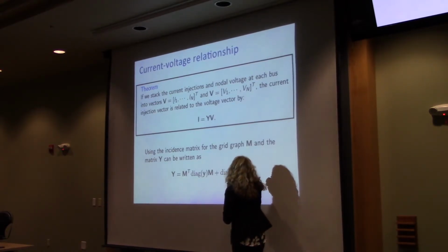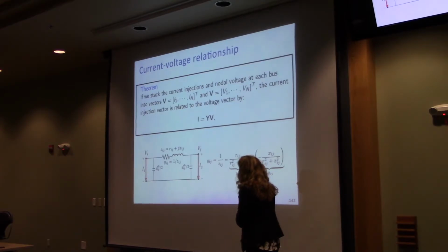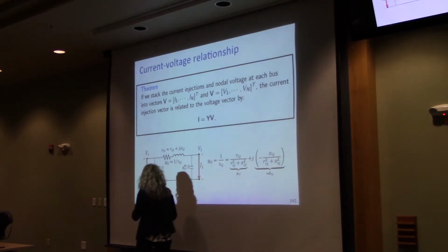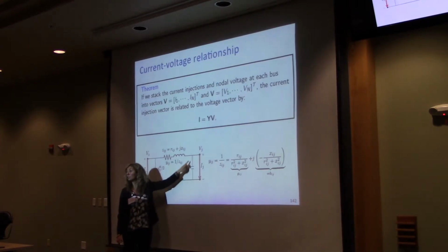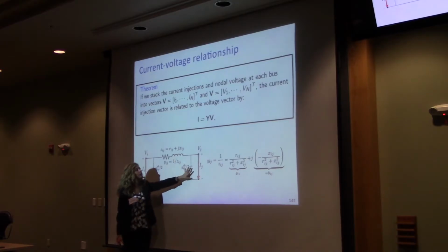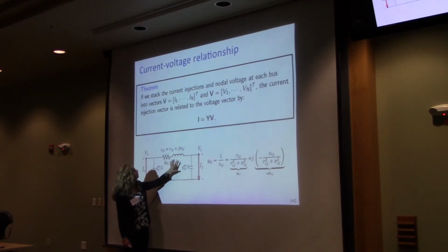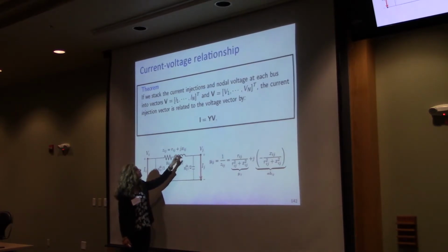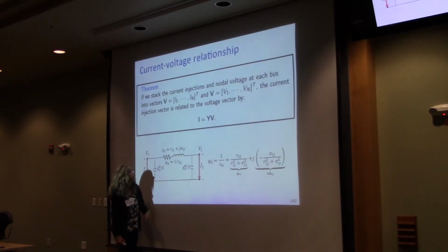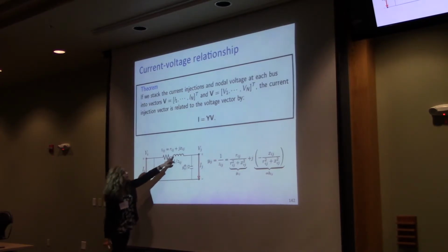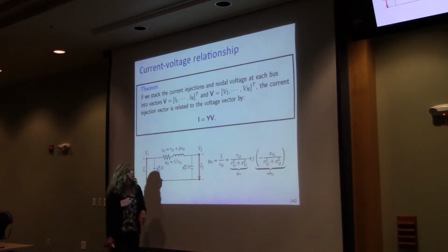which is, again, the transpose of the incidence matrix, times what are called shunt impedances. And this comes from the fact that the transmission line has a resistive and inductive effect, but it also has a capacitive effect, right? So that shunt line comes from the fact that if you write the equations of an entire transmission line as a two-port system, in general you can utilize this equivalent model where you have resistance, inductance. These are basically the resistance Rij, and X is the parameter that goes with the susceptance. It's called susceptance, with the inductor here. And the capacitive effect is instead represented by this shunt admittance.